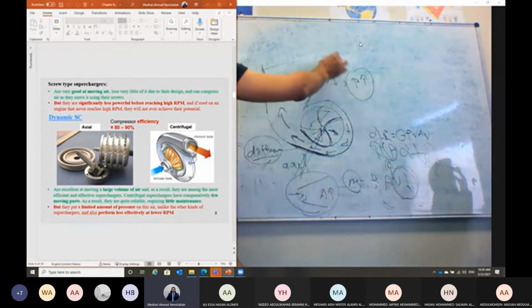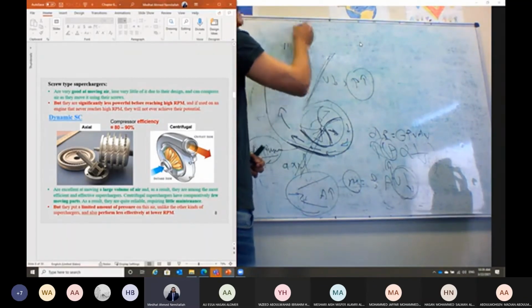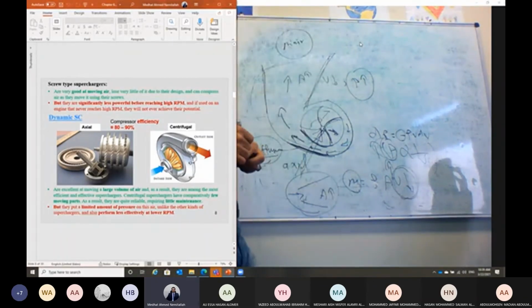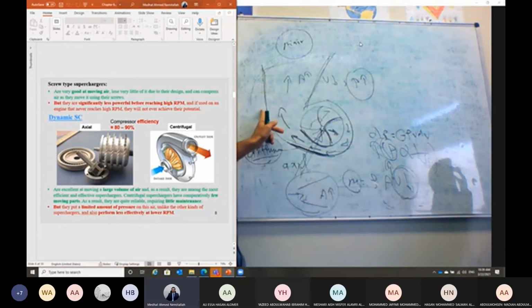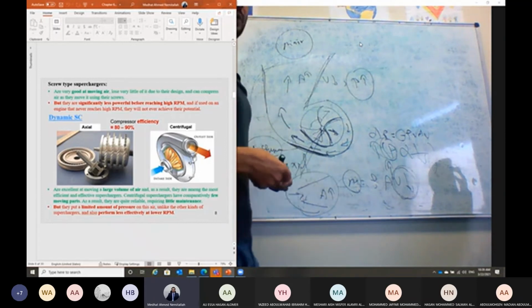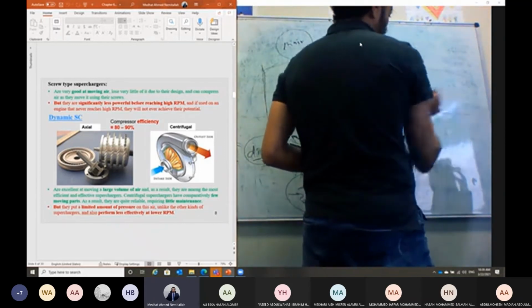This flow compressor is characterized by a lower mass flow rate of air, or in the case of a small engine. Usually in cars, the mass flow rate of air is small. So in most cases for a turbo supercharged car, we have this design, which is a centrifugal flow design. But in case we have a turbine for a jet engine or something, then in this case we need a higher flow rate of air. So in this case we have to use what's called the axial flow compressor.